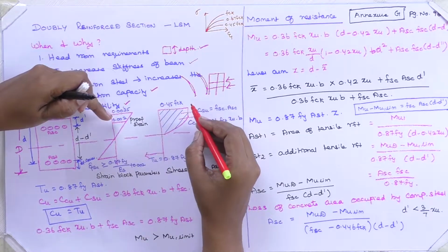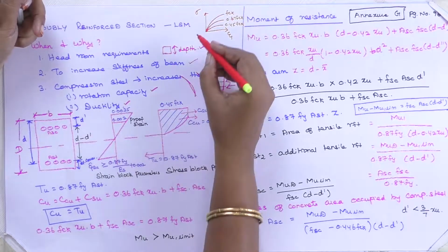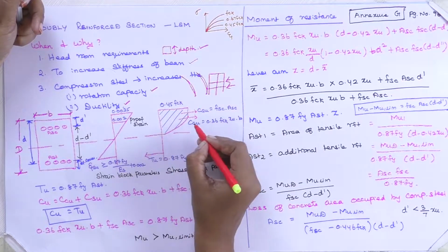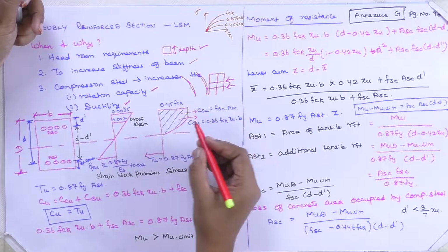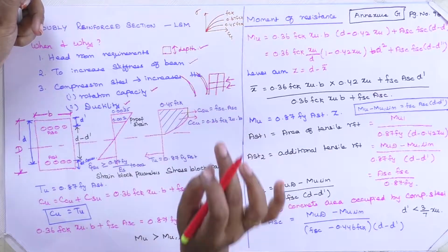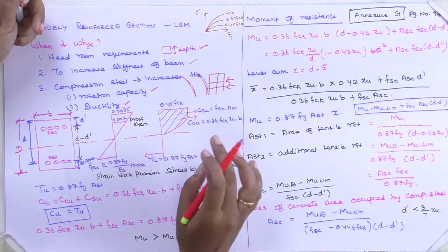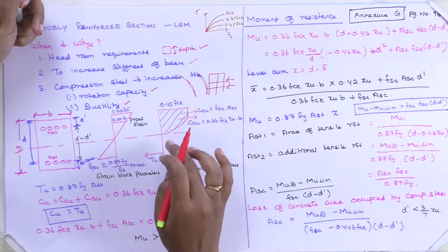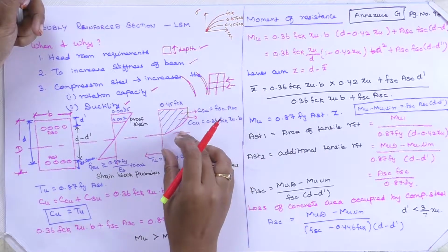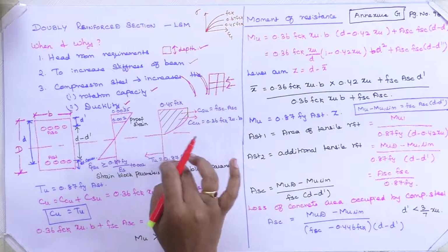Okay, till this 0.002 proof strain, I will get some linear value. After that my strain is in a parabolic fashion, right? Up to this I will get some straight line. After this the curve will be changing around. This is the stress block for my concrete. Here you may ask why you don't put any stress block over here in my tension region. In my assumption I have told you that the tensile strength of concrete should be ignored here. The concrete won't take any tensile strength, so you should ignore it here. Only steel is provided to take care of my tension.